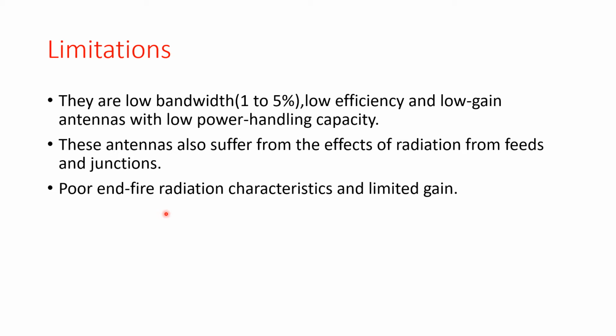So usually when you consider the different types of antennas, they are very poor end-fire radiators. And also the surface wave excitation in these antennas is an added limitation. So these are the basic limitations of the antenna, and the above limitations can be addressed by either using a thick substrate or cutting slots in the metallic patch.